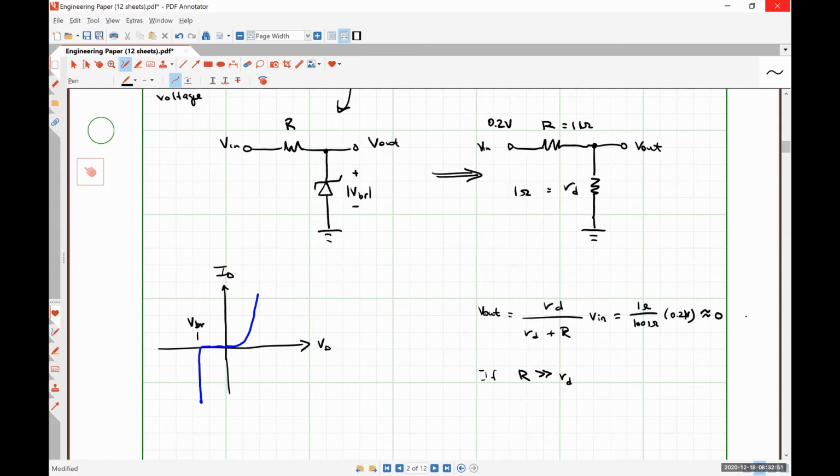Furthermore, the characteristic curve tends to be most vertical for Zener diodes with breakdown voltages close to 6 volts. Thus, Zener diodes with a 6-volt breakdown voltage provide the best performance as stable voltage references. Saying that, just to be very clear for some of you guys who may choose to do the 48-volt Zener diode voltage regulator project, means you just put 8 of them in series. So just a heads up, if you want it to be very stable, that's a way to go.